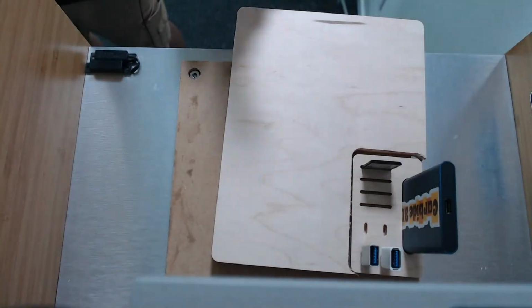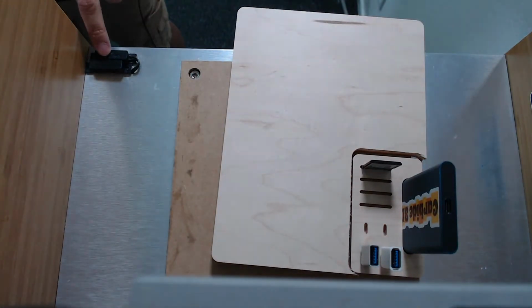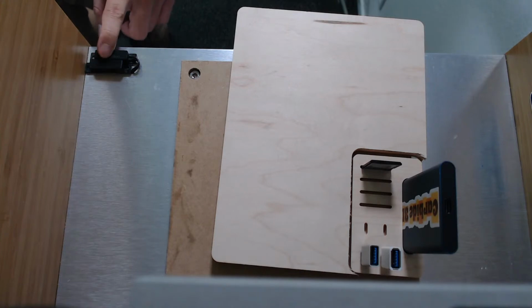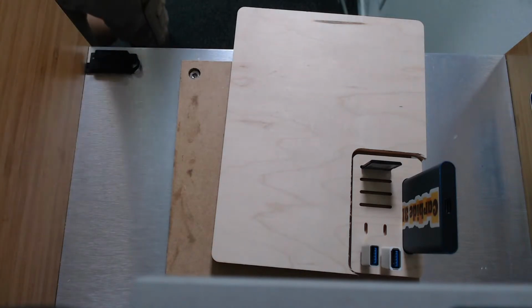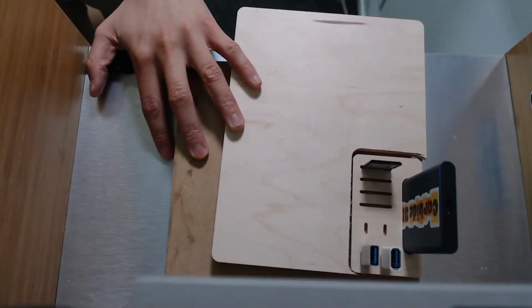Also, if you're curious, last time I was stymied by this machine. Turns out there is a door interlock here. It's a safety feature that we had on earlier machines, and I think the European machines and education machines. And I forgot that with the door open, you really can't jog the machine or do anything at all.